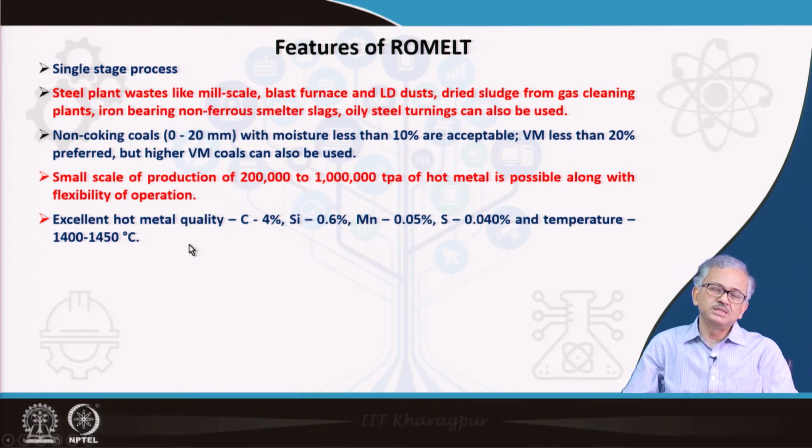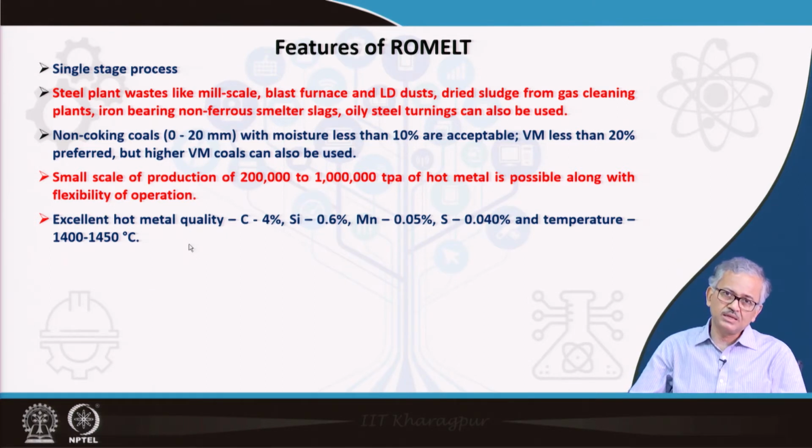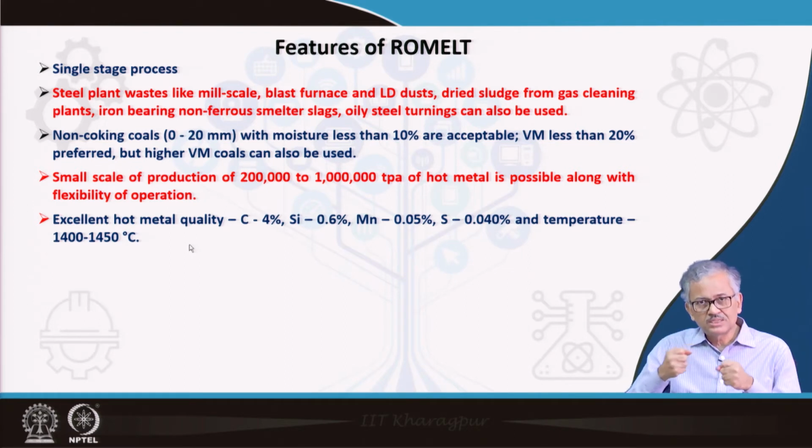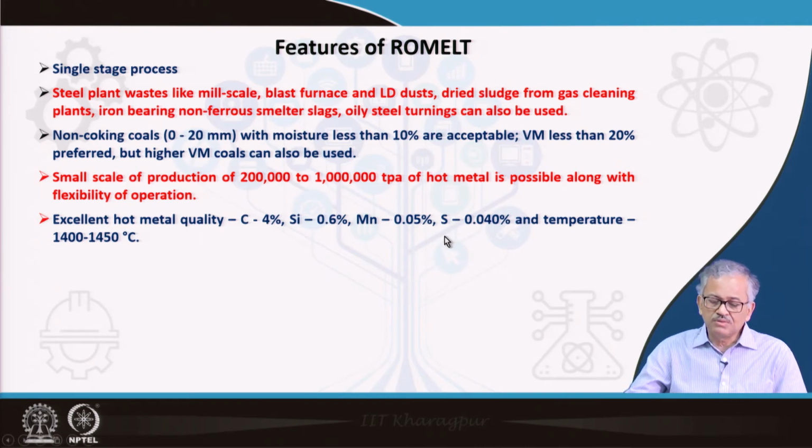And here in the single stage reactor, one thing is the slag that is generated. Basically you can find the emulsion forms in the upper part, and there some slag metal partitioning takes place because the slag contains FeO. The FeO makes the slag a little oxidizing there, and then they can partition some amount of the phosphorus and sulfur. That is why you can get a very low phosphorus also.